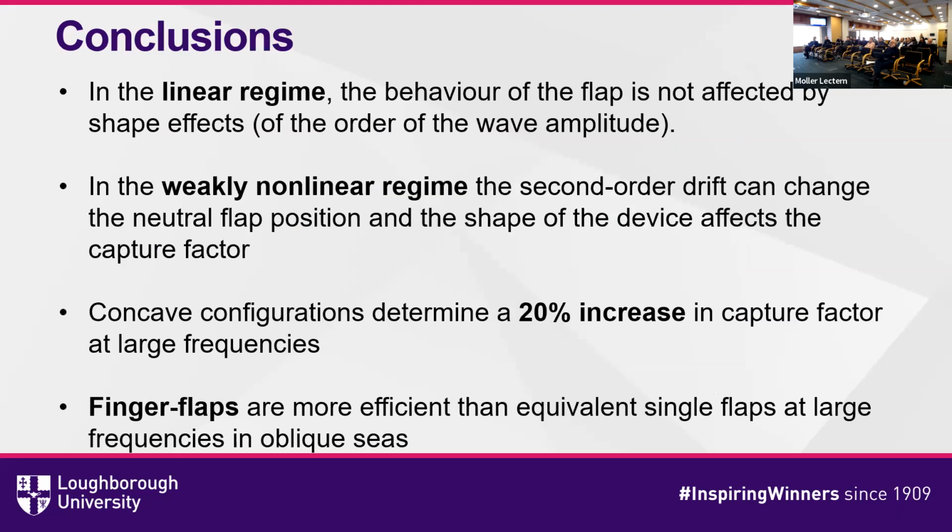So to conclude, I showed you that in a linear regime, the device is not affected by shape effects, if, of course, they are of the order of the wave amplitude. In the weakly nonlinear regime, we have the emergence of a second order drift, which changes the neutral position of the flap, so it no longer oscillates with respect to the vertical axis, but with respect to an inclined axis. And all these nonlinear and shape effects affect the capture factor of the device.